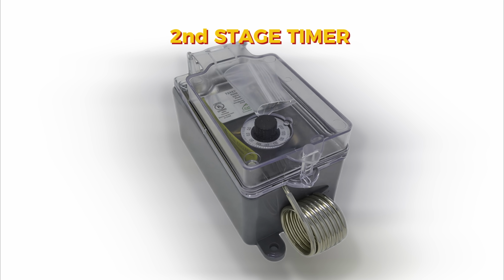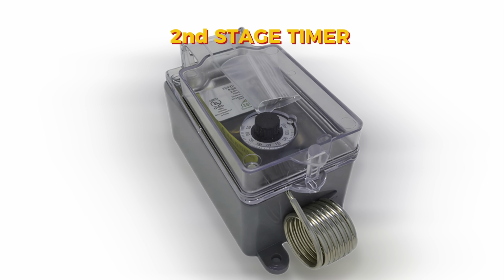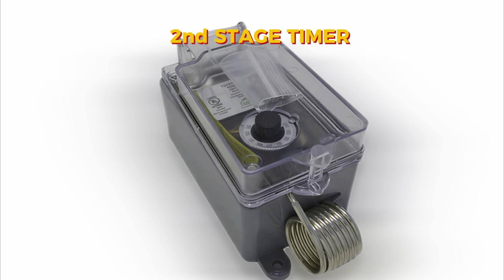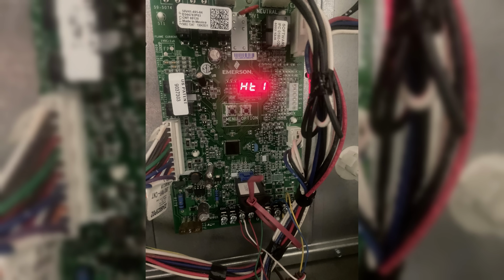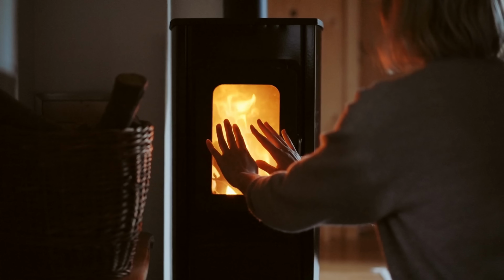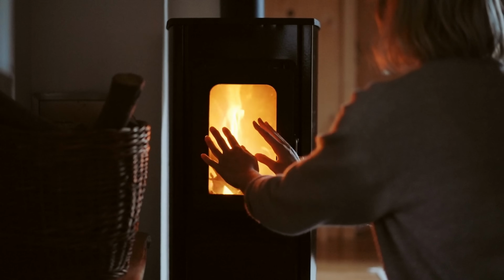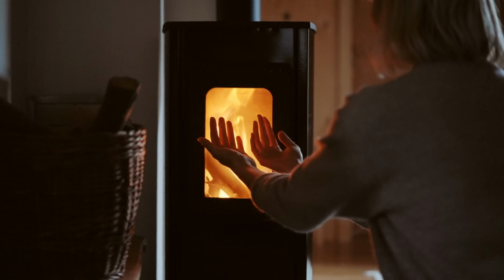There's a second hidden setting in that menu called the second stage timer. If you have a 2-stage furnace, the thermostat is often programmed to upshift to high heat mode if the goal temperature isn't reached in 10 minutes. This is like flooring the gas pedal to get to a red light. We are going to push that timer back to 20 or 30 minutes. This forces the furnace to stay in its low gear, high efficiency mode for longer, which is much cheaper and provides a more consistent, gentle warmth.